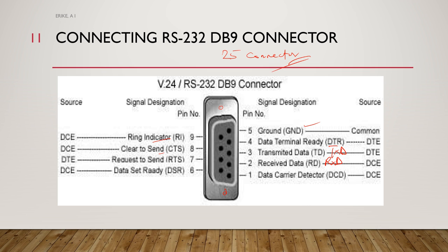So if hardware data flow control is required for serial transmission, various control lines of the RS232 connections are used appropriately. The control signals are implemented mainly for modem communication, and some of them may be irrelevant for other types of devices.